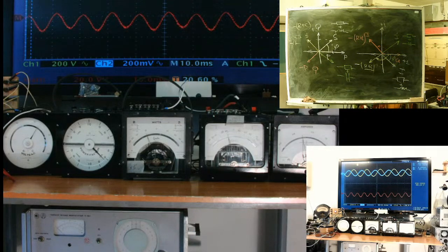It will be a regime or mode when the machine carries an active load, but it also supplies reactive power to the grid. The machine is overexcited. Exciting current is above 1 pu, above 100%, to supply the network with reactive power.